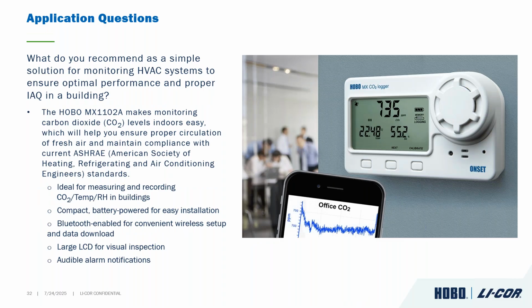Another frequently asked question that we receive is, what do you recommend as a simple solution for monitoring HVAC systems to ensure optimal performance and proper IAQ in a building? So the HOBO MX1102A makes monitoring carbon dioxide levels indoors easy. This will allow you to help ensure proper circulation of fresh air and maintain compliance with ASHRAE, which is the American Society of Heating, Refrigerating, and Air Conditioning Engineers.